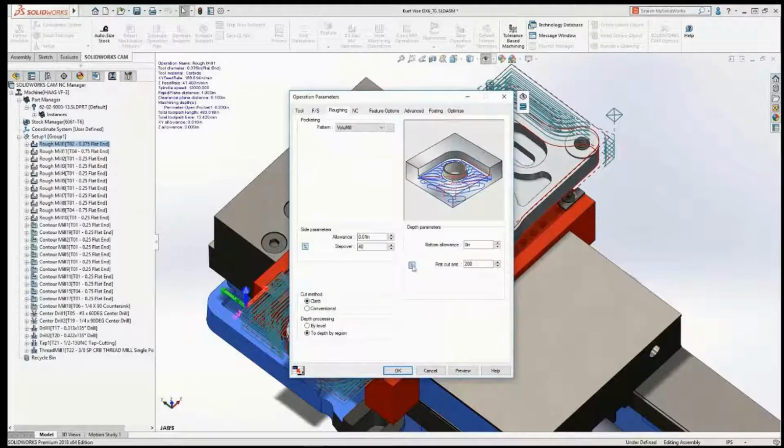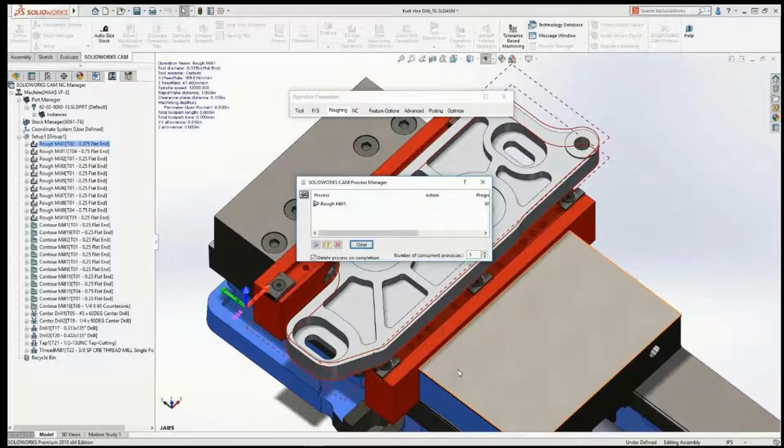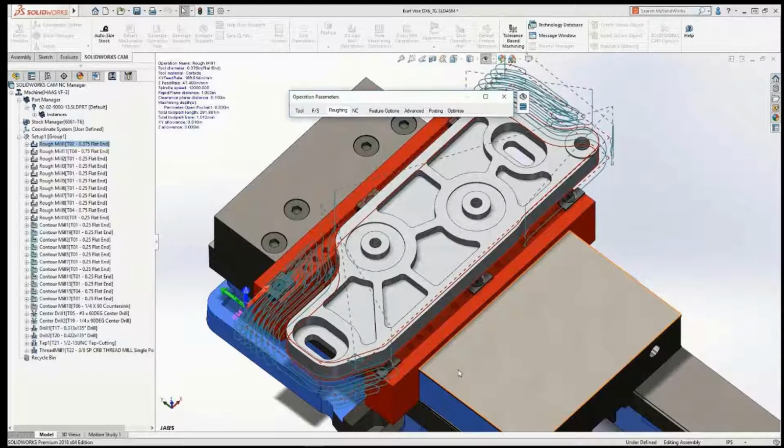So after I have done that, I will explain how the volume technique works. It's increasing the depth of cut and reducing the step over, which means the whole end mill will cut with the full cutting edge. So that's a good advantage. So we kept the strategy as it was. Let it process and check the final time.